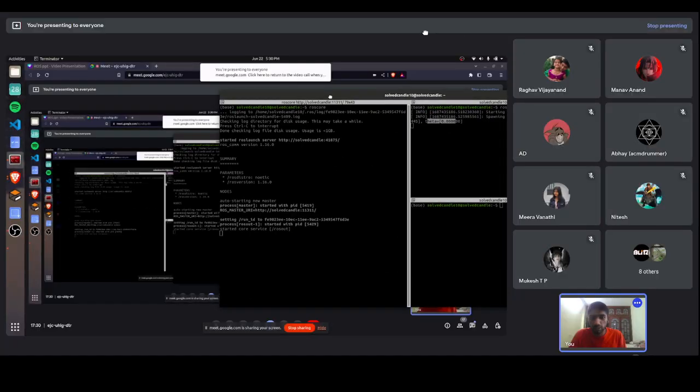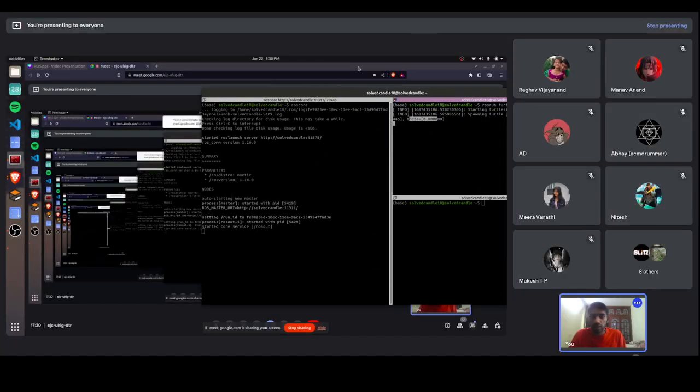I hope it is visible. So I'm running my ROS commands here on this terminal, and this is something which is created when I give this command called rosrun. So I give this thing called rosrun turtlesim turtlesim_node. So this is what gets deployed.